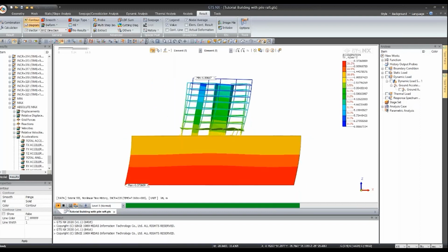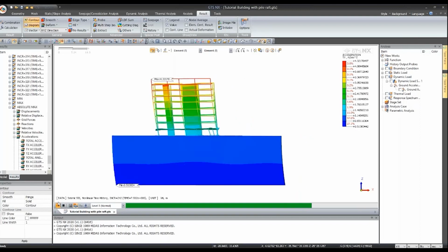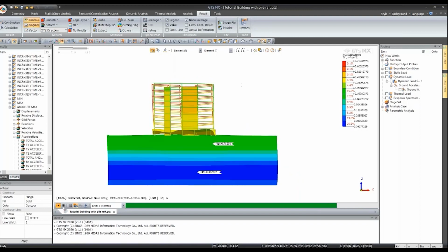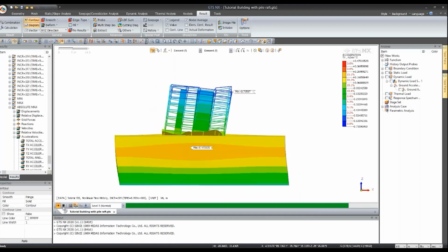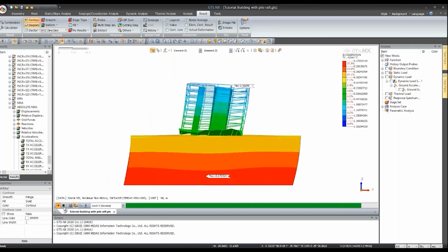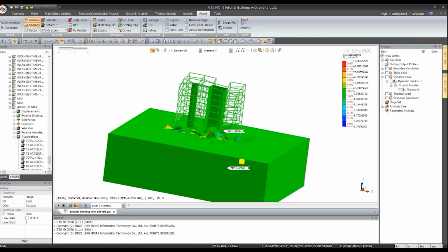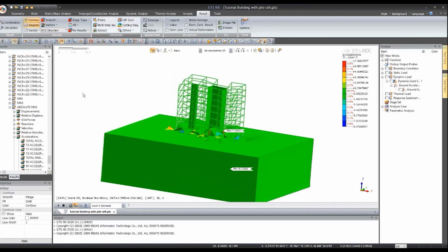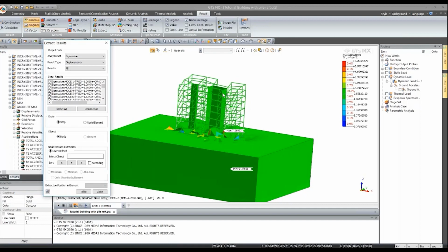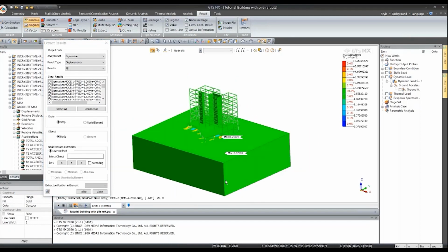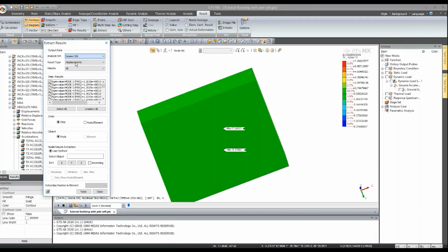So I would like to draw an acceleration versus time for this model. And as I said, the roof is not important for now, hence I have deactivated the roof. So let's go for extraction. Here we have an extract option to extract whatever results you are interested in. Let's go for actual deformation. Yeah. So here, go for seismic analysis. I have given the name as seismic. And now accelerations.